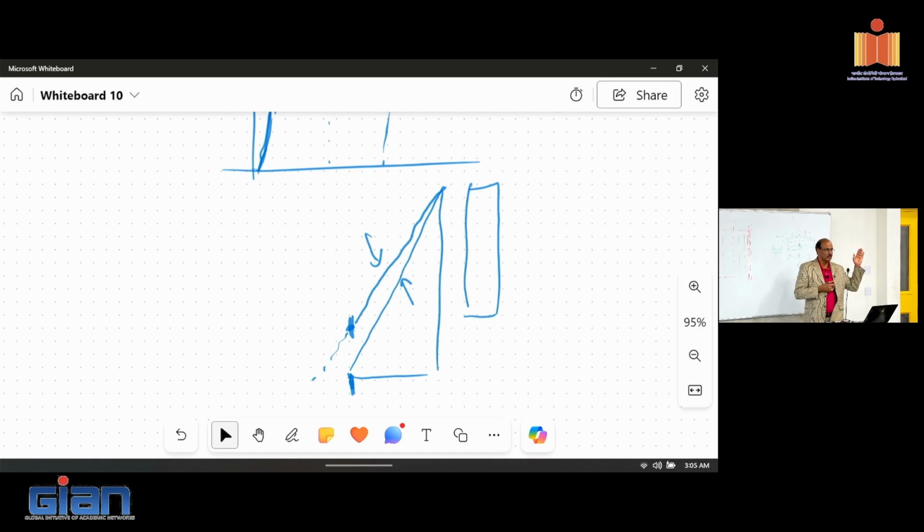So if you design for shear reinforcement based on cast in place, you put couplers and establish continuity, now your shear demand is going up, that could potentially create a shear failure in the column. It's so much a concern in bridge structures, people have seen it even happening. So typically it has happened in real life. In building columns, normally the shear criteria will not govern also. Yeah, exactly. Reserve capacity. Yeah, but as a designer, somebody needs to understand this, right? And make sure that it's not a concern.